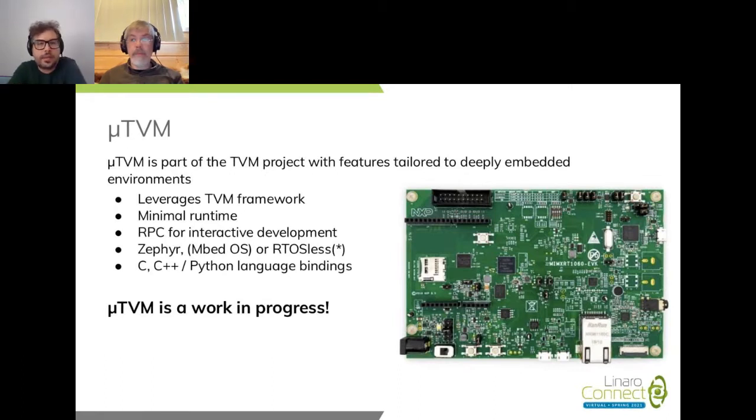One of the nice things about TVM, as Tom mentioned, is that TVM can target microcontrollers, and for that specific runtime, there is a minimal runtime which leverages the TVM framework and which implements an RPC server, and is also able to run on top of Zephyr or any other RTOS, and also RTOS-less, without any RTOS under it.